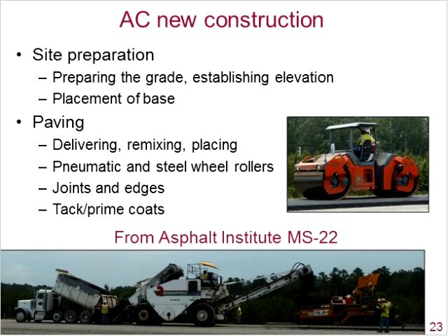Asphalt concrete, or AC, new construction. Note how I put new construction under here. This is assuming that you're building a brand new road. Things change if you're rehabilitating a road, if you're doing maintenance on a road, or if you're putting an overlay on an existing road. But assuming that it's new construction, you need to prepare your site, which includes preparing the grade and establishing your elevation, just like the PCC pavements, and then you place your base down.